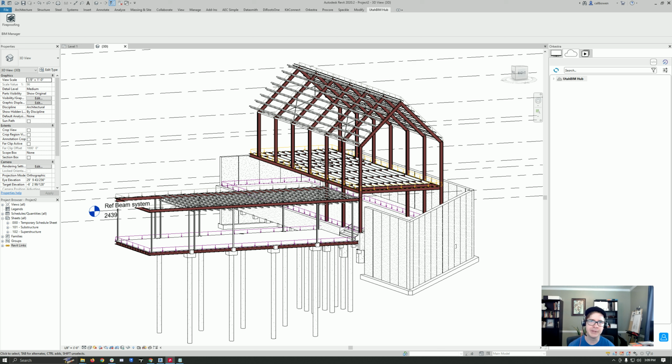This is also more helpful than Navisworks clash tolerances, because those are set across the whole clash test, versus our app, where you can pick a whole bunch of steel elements and set them at 1 inch, or pick one and set it at 2, and then another one at 3, or groups set at 3.5, whatever. So you can have different thicknesses for all of your fireproofing on your steel elements, instead of having to rely on just whatever the greatest denominator is for your Navisworks clash. So let's take a look at what this looks like.